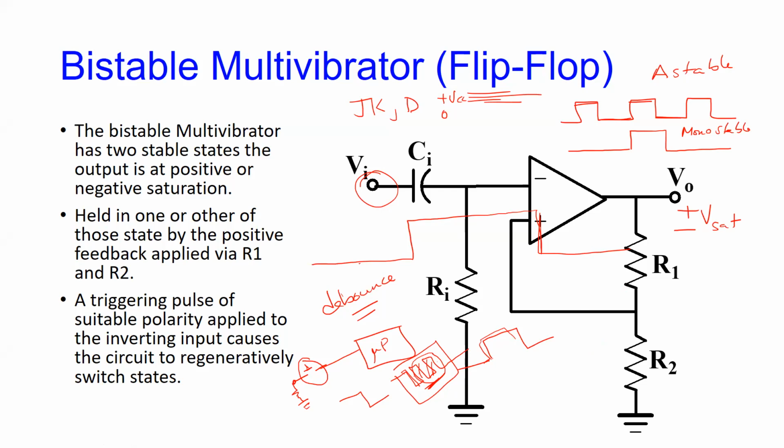All right. So monostables are used a lot in switch debounce applications to clean up mechanical contacts. This goes back to when you connect the real world to circuits, a lot of funny things happen, and many of the applications of all these little circuits we spoke about are to clean up that connection between the real world and the electronics. The analog and digital domain, yeah.